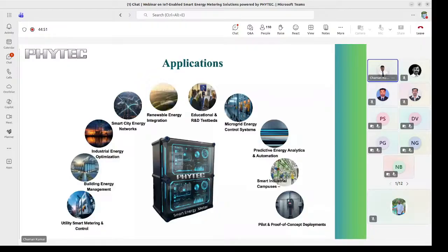So when they send the data, they send the information that I am this meter and I am sending this data. Accordingly, the DCU understands which meter the data is coming from, and then it will aggregate the data and send it in the DLMS format only. But in the HES, once it goes to the head end system, it will decrypt that DLMS format, and some encryption is also going on and some security is enabled. All that will be done in the HES.